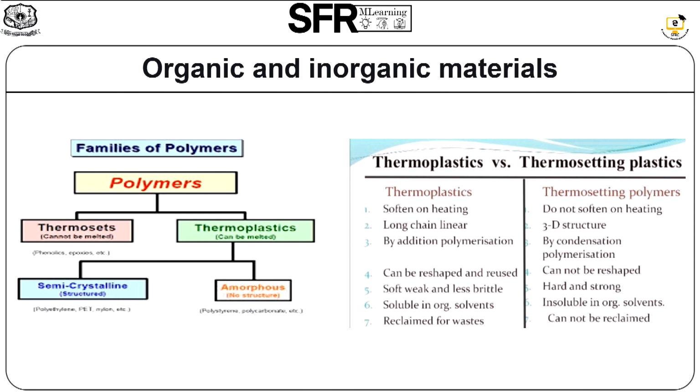Thermoplastics: on heating, this material becomes soft and hardens again upon cooling, for example nylon, polythene, etc. Thermosetting plastics: these materials cannot be re-softened after polymerization, for example urea formaldehyde, phenol formaldehyde, etc. Due to cross linking, these materials are hard, tough, non-swelling and brittle.